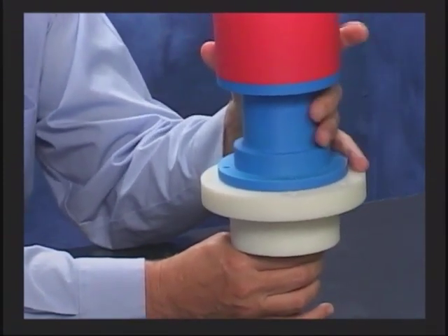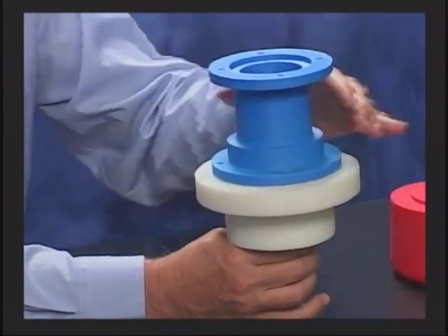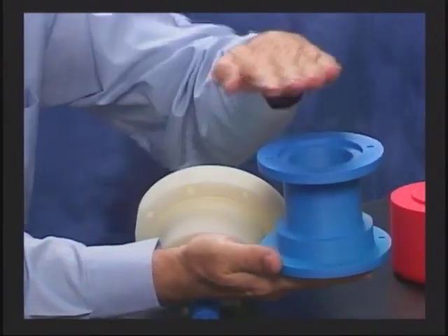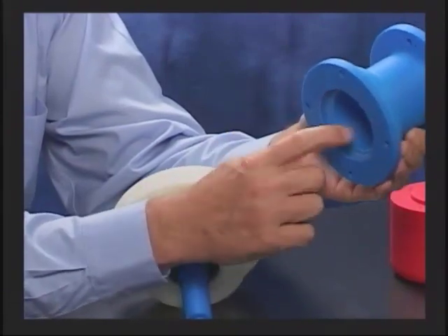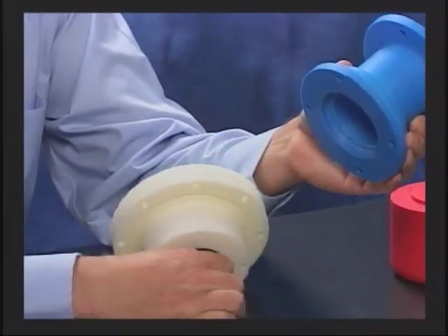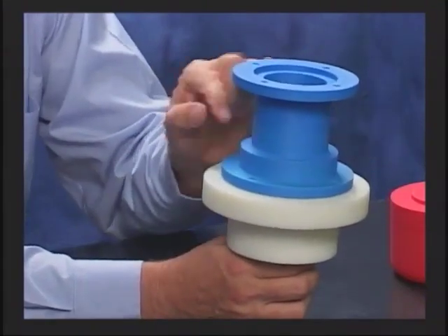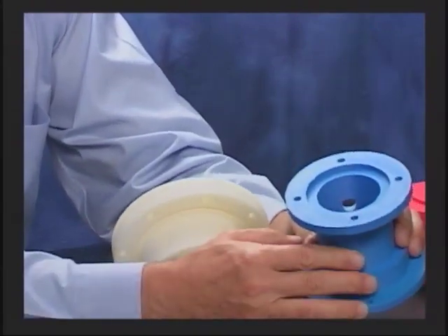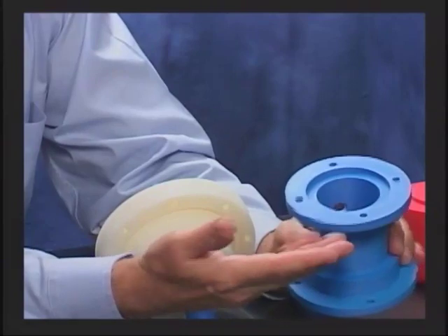Also, another thing we had to worry about was that on this adapter by itself, remember the datum on that was the bottom face. Didn't we say the face was the datum, and then this pilot was the datum? We did that because that's how the parts locate to each other. Those were our leaders, and then we told the followers how much they could follow along by. And when we did that, we came to that top face because we had to say something about that face.